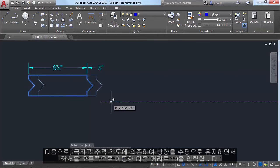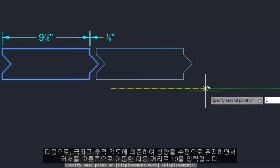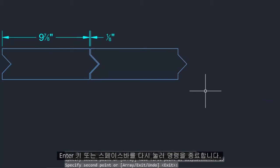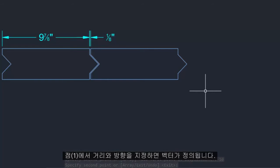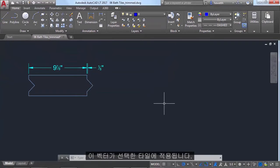Next, move your cursor to the right, relying on the polar tracking angle to keep the direction horizontal, and then enter 10 for the distance. Press Enter or the spacebar a second time to end the command. When you specified a distance and a direction from a point, you defined a vector. This vector was applied to the tile that you selected.